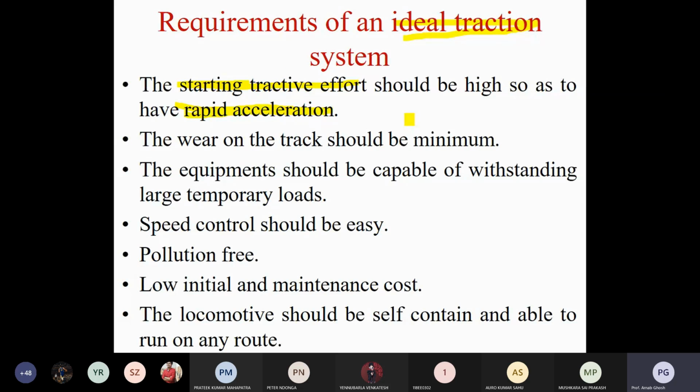But right now vector control is coming, so the induction motor can be controlled in the form of vector control. Some portion of the generalized study of machines you have already gone through, or maybe you will read this semester. I think in Machine 2 it has been covered already. We convert the entire concept into the DQ model, three phase to two phase configuration.